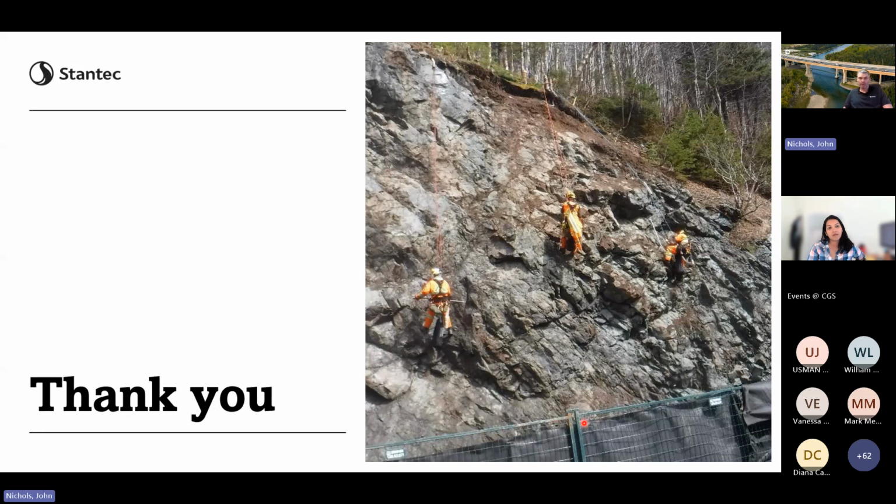Shale is typically a very weak rock, but then I would probably also apply anisotropic conditions to that slope. So I would look at it from the rock mass, but the parameters I would assign, there are a couple of methods you can use in design software, these anisotropic methods, like the Snowden method, which is one very popular one we use.